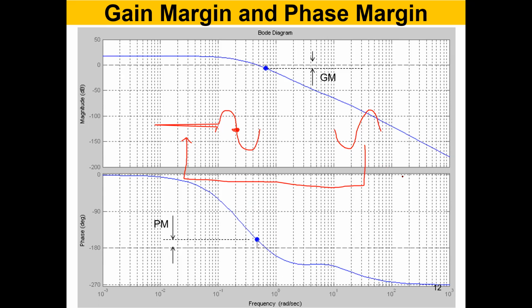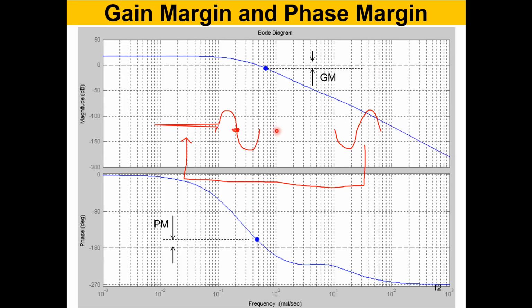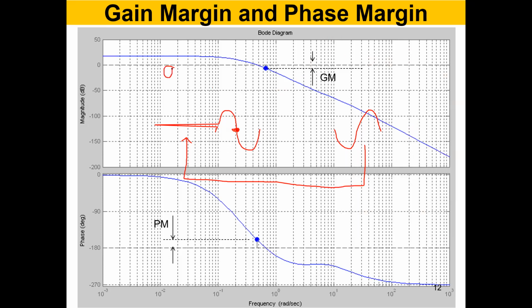It's a bad idea. Because what you're supposed to do in feedback is in fact negative feedback. You want to subtract this signal from this signal. That is what is called negative feedback. You see the block, so this is the summing block and this is the reference signal. And this is the feedback signal.